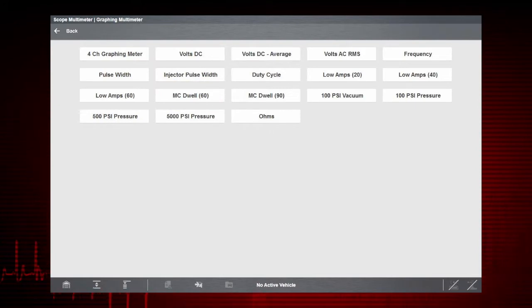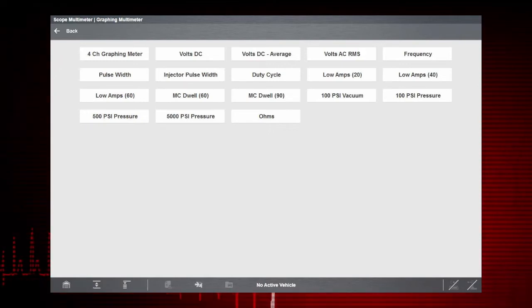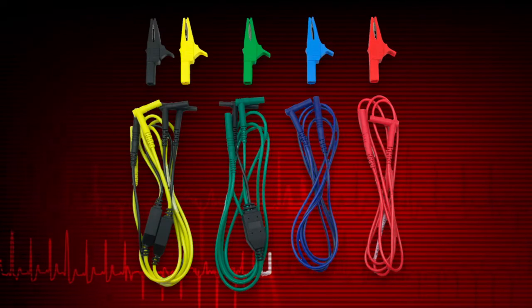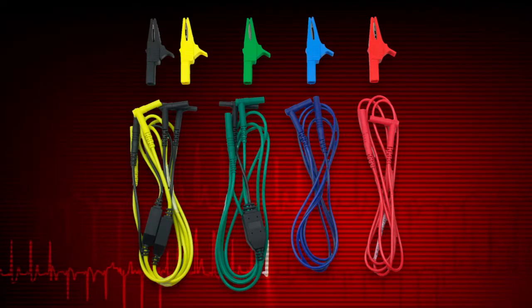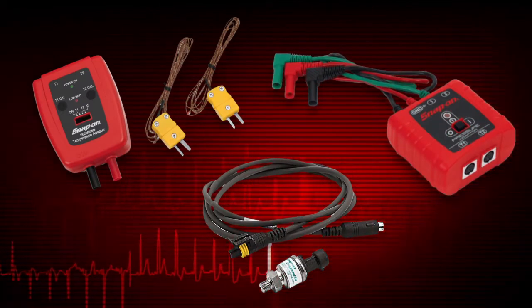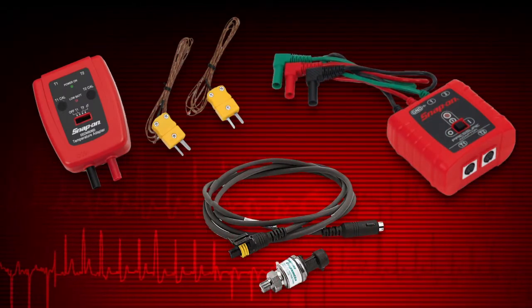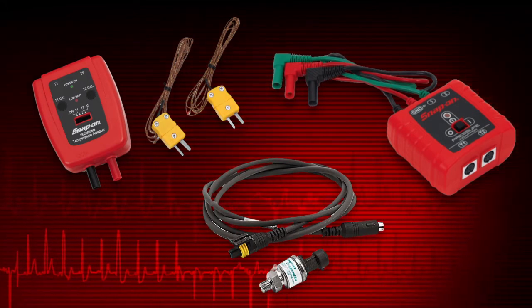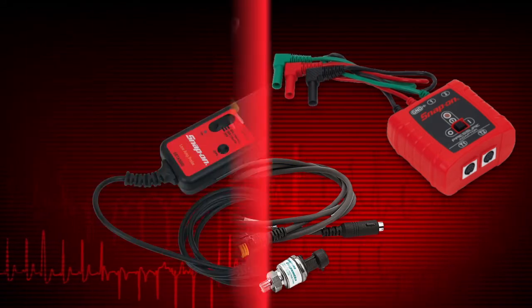Before performing a resistance or current measurement, calibrate the meter to ensure accurate results. See the user manual for the calibration procedure. Most of these tests can be performed with the standard leads included with the tool. Here are some optional probes available for specialized tests to detect glitches in pressure, vacuum, and temperature in automotive applications.